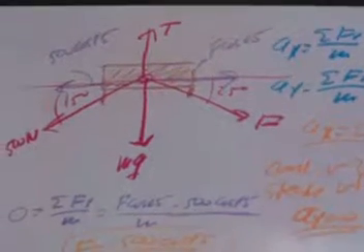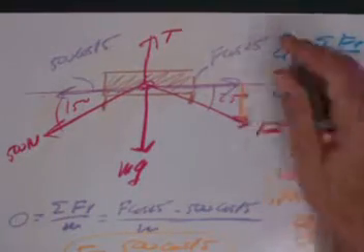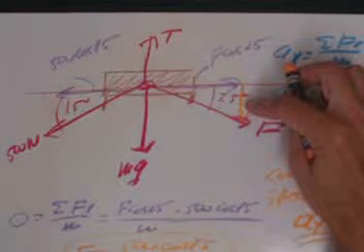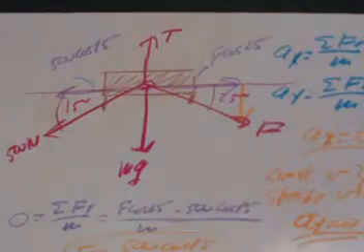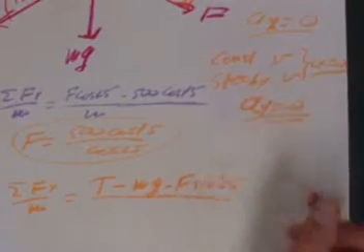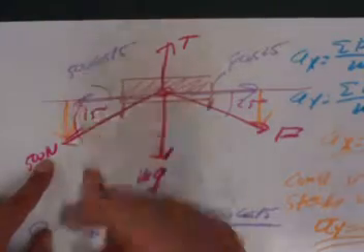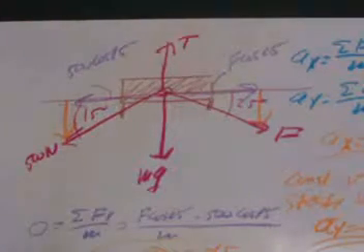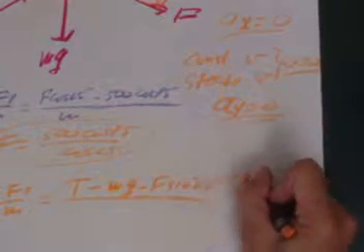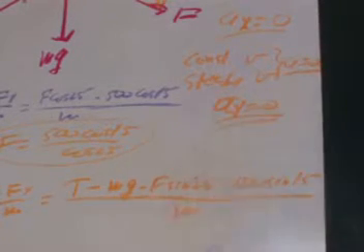And you cannot forget about the y components of these two forces here. This force over here definitely has a y component right there. I won't write it on here because the drawing's getting a little bit crowded, but this is going to be an F times the sine of 25, and it points down also. So I'll label this a minus F times the sine of 25 pointing down. And this vector also has a downwards component, which will be 500 times the sine of 15. So we'll add that on here as well, minus 500 times the sine of 15, and all that's divided by m.